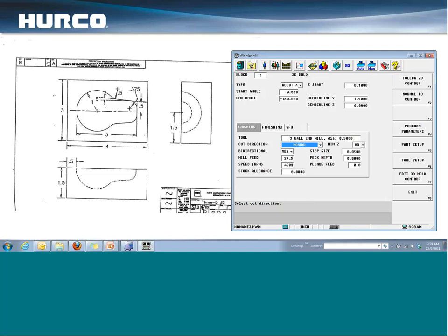At this point, can you click the Finish tab and use that for a finish cut? Yes, that'll work the same as any other data block. You can click on that, give it the same tool or a different tool, and then that'll take it to size. And also, you control the step size there also? Yeah, it'll ask you for a finish step size as well.